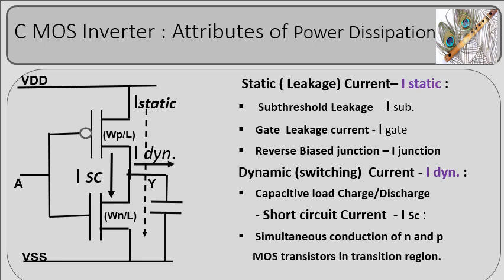The power dissipation in a CMOS inverter is influenced by several factors, categorized as indicated below. Dynamic power dissipation occurs due to switching activity of charging and discharging of capacitance currents and the output voltage switching between high and low states. Short-circuit power dissipation occurs in switching transition, during which both NMOS and PMOS transistors are momentarily on, causing large current conduction between the supply rails VDD.